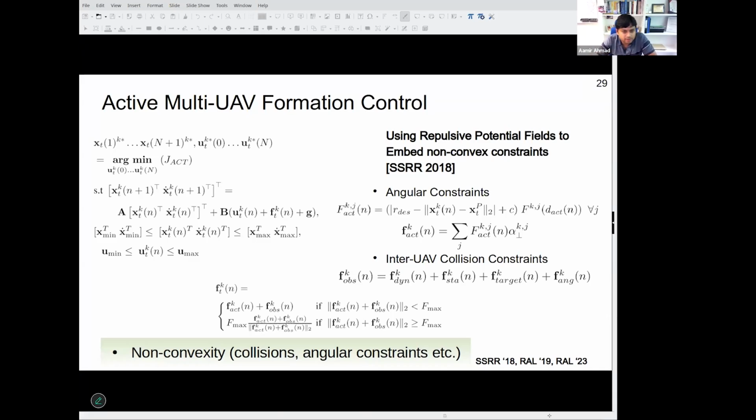Based on another work that we have done before, which I don't want to go into detail today, we address the problem of how to still work with non-convex situations and constraints by converting them into a force value using some potential function. We embed them directly into the linear system dynamics constraint, which is this expression here in the first constraint of the MPC. Although we do locally convexify this problem so MPC can handle it, it does not remove all associated problems like local minima.